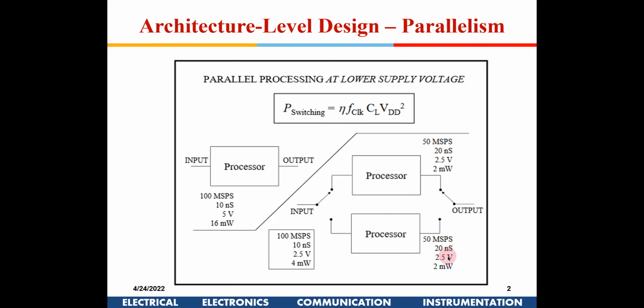and that is why the power supply voltage I have reduced to half. So a reduction in power supply voltage increases the delay. Okay, but I can afford to have double the delay, and hence I have decreased the power supply to 2.5 volt and 2.5 volt here.